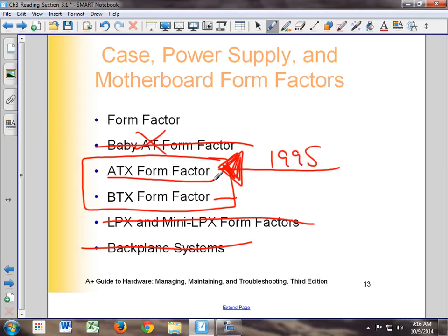Here's one old. Whereas with this one, if I have this computer right here and I want to upgrade it, I can just buy a new ATX motherboard. Unscrew this one, take it out, maybe use the same CPU fan, a different CPU, same memory. I can almost use everything on this PC over again for a full upgrade. This one, I can't use the biggest component, which is the motherboard and the case. I have to start all over. So, your research project's all going to be ATX.